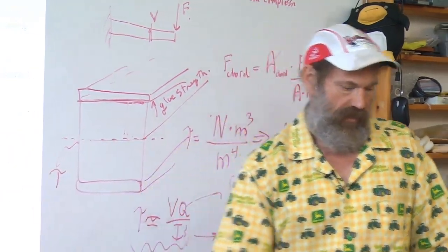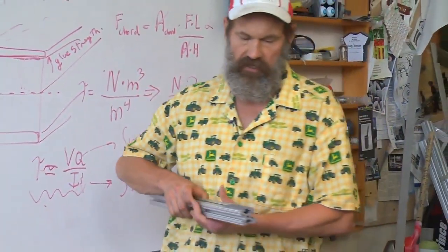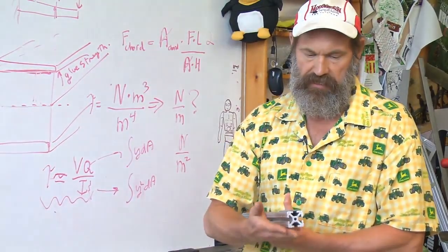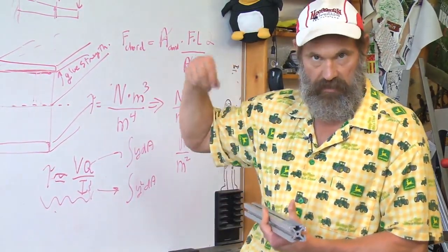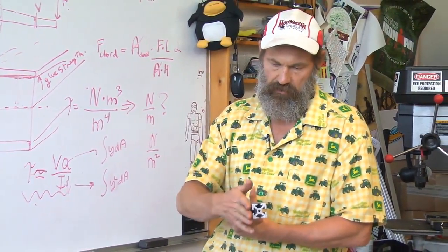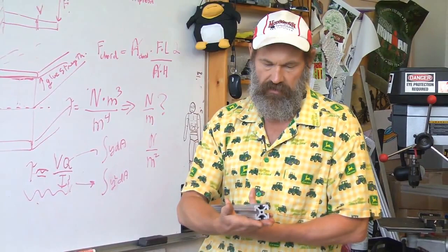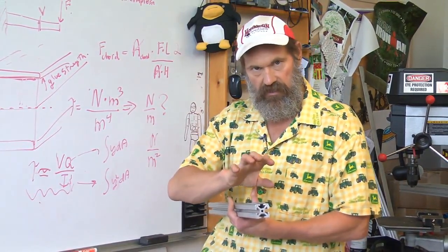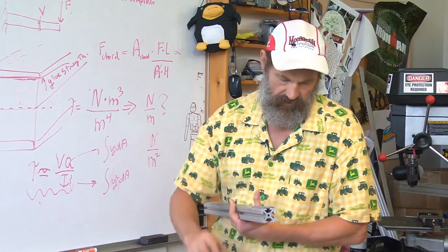Or you've got something like this beam we talked about earlier where we want to stiffen it up by applying plates in the regions between other members that are bolted to this modular stuff. And we want to apply plates to close this structure so it becomes a closed form structure so we get high torsional stiffness and will increase our bending stiffness also.